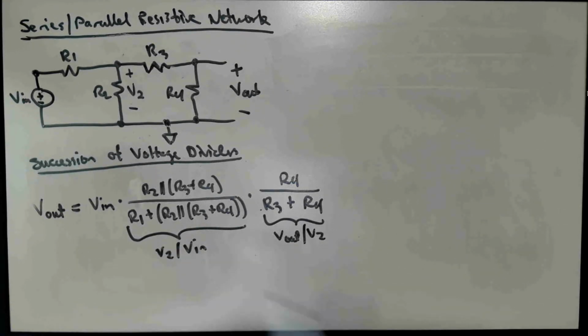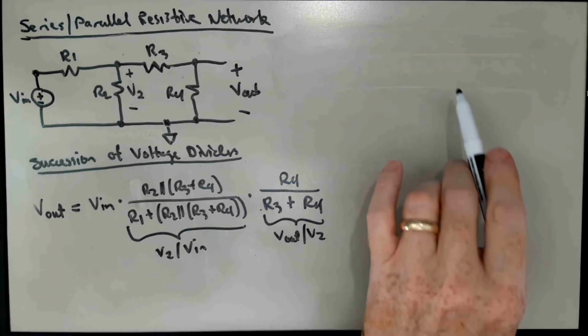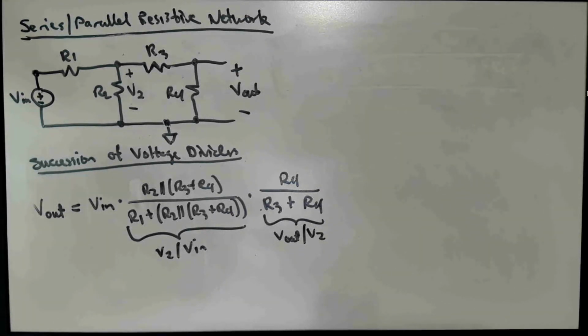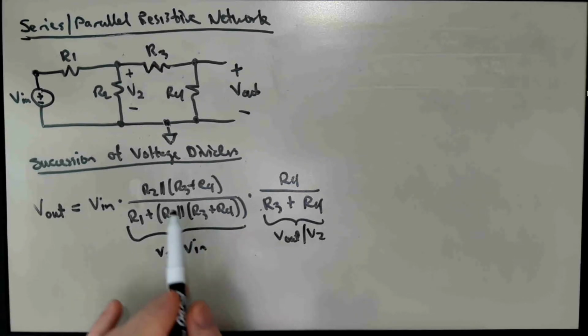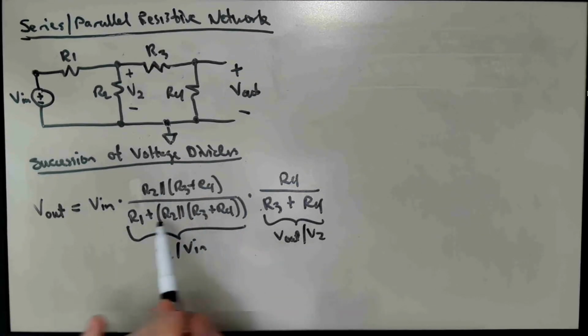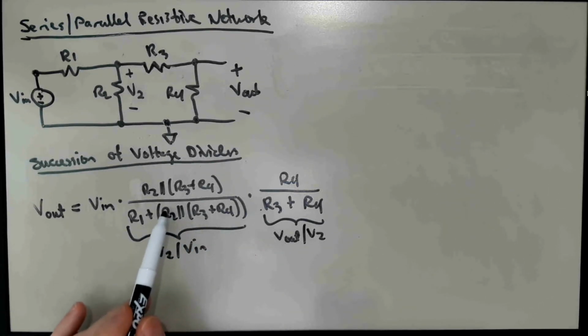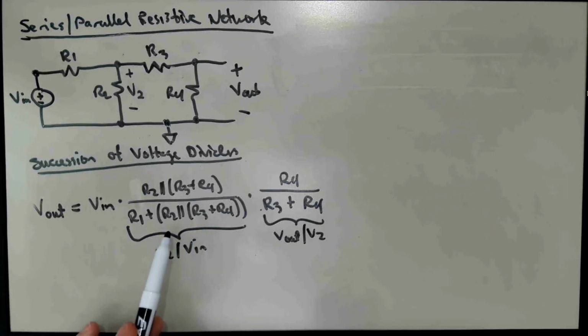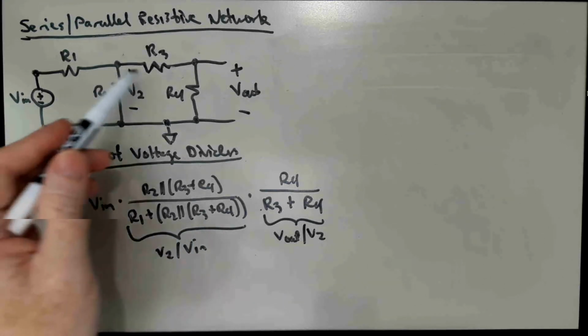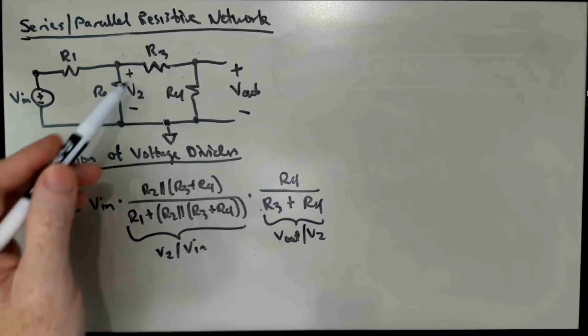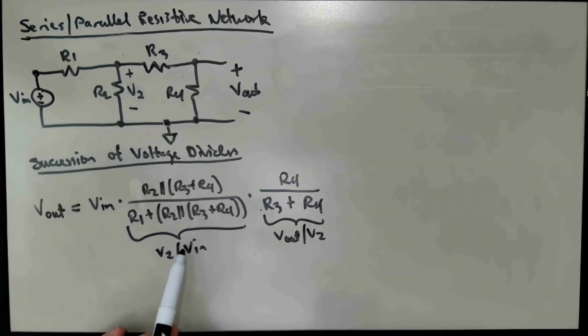And so this expression, in contrast to the one that I erased from up here, is not just simply the sum of products of some circuit elements divided by the sums of products of some circuit elements, but these circuit elements are grouped in natural groupings that correspond to the structure of the network. They're interpretable as things like voltage divider ratios.